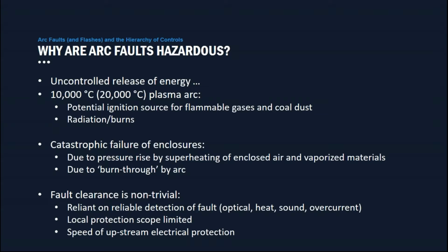Clearing a fault is non-trivial, so we are generally reliant on being able to detect the fault, either through optics or heat or sound or overcurrent. Then we have to initiate some protection upstream of the fault and hope that it is activated successfully and also within a reasonable time frame.